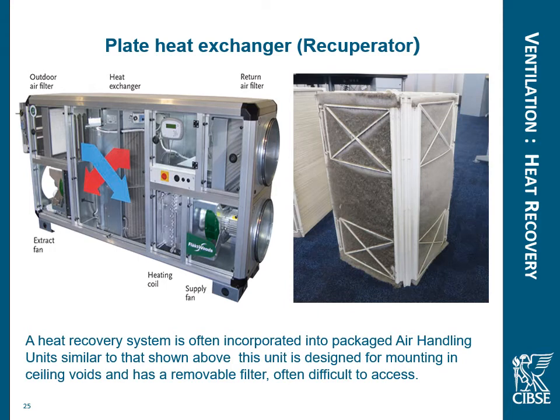Now the smaller units, as we can see, is a filter out of one on the right hand side there, tend to sit above the false ceilings and perhaps in cupboard areas, and we don't always know that they're there. These are small ones that serve individual rooms. These have filters built into them, quite difficult to maintain, and in my experience, quite often they're not maintained very well at all, because the filters are quite difficult to get out, and these are quite often in places difficult to access.